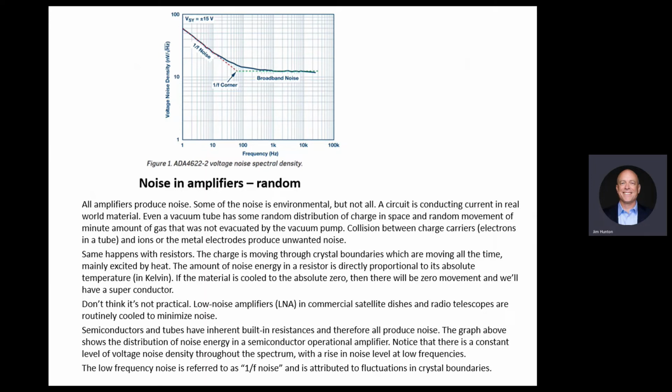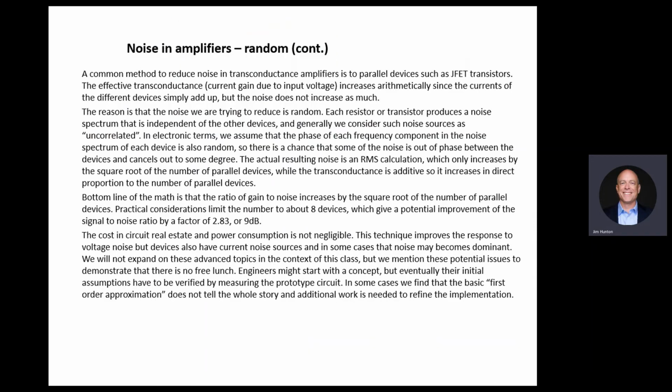So this is the inherent noise of a device. If you look at nanovolts per root hertz, it's the square root of the power, essentially. The lower level is better. You'll see all these JFETs or new op amps with 0.7 nanovolts per root hertz.